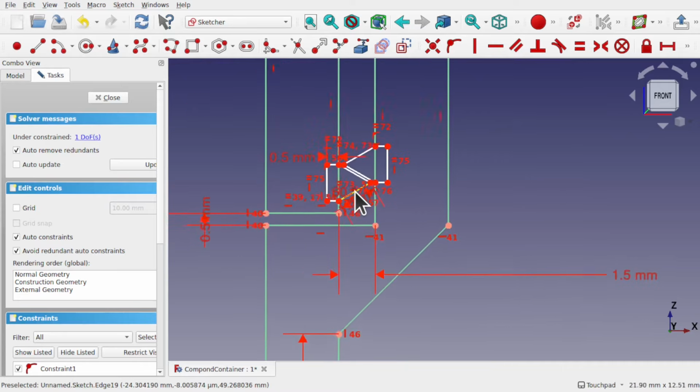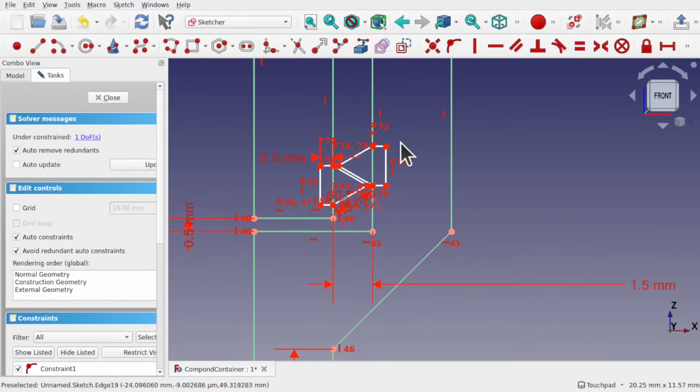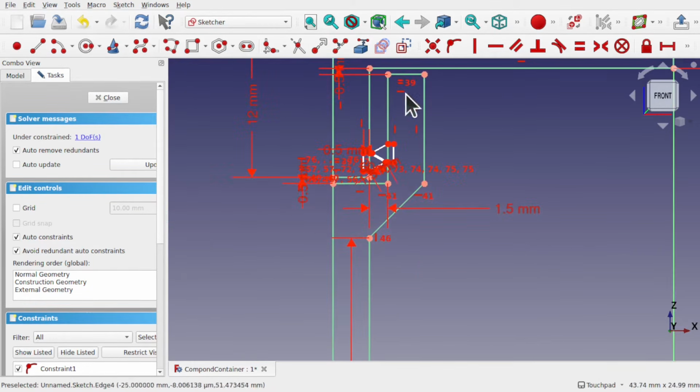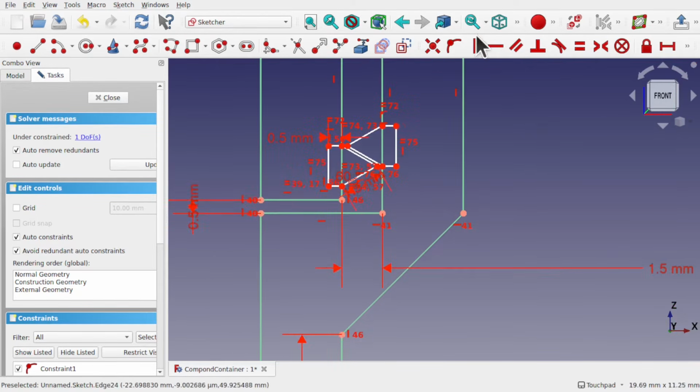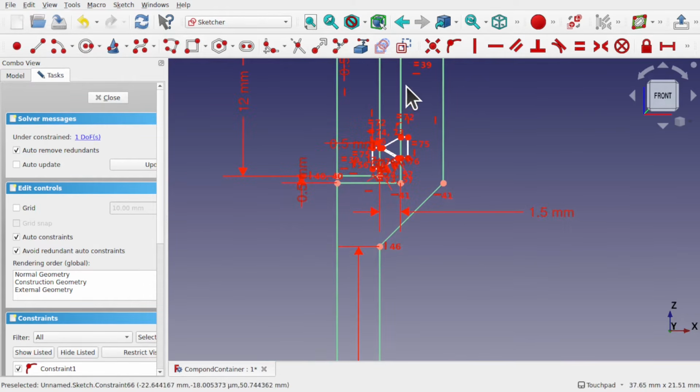Now a characteristic of a screw top lid is that the threading itself is not like a normal screw. They don't have as many turns, so we don't need as many turns. And also they don't go all the way to the base. Because if you think about if we have a screw thread in here, then if we don't go all the way to the base, it makes it easy to put the lid on rather than trying to find the screw thread at the base. Also, it doesn't go all the way to the top either.